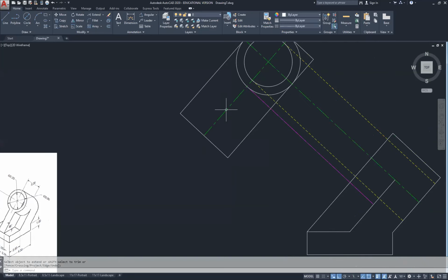So I'm going to take this line, offset, 0.5, enter. Take this line over, take this line over, and that gives us a grand total using a line dimension from here to here of 1.